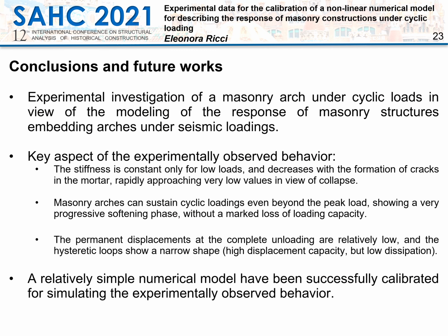In conclusion, an experimental investigation of a masonry arch under cyclic loads has been carried out in view of the modeling of the response of masonry structures embedding arches under seismic loadings. The key aspects of the experimentally observed behavior are the following. First, the stiffness is constant only for low loads and decreases with the formation of cracks in the mortar, rapidly approaching very low values in view of collapse.